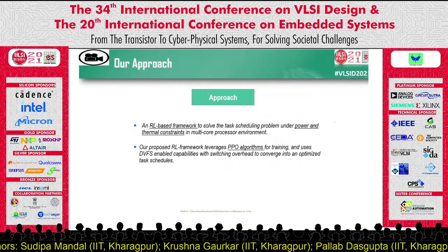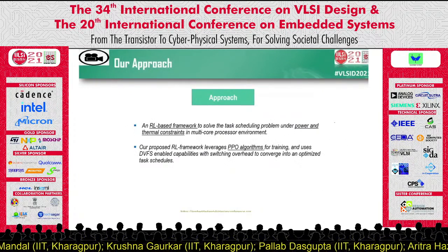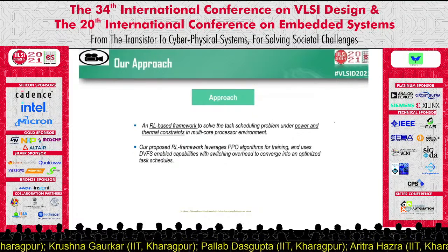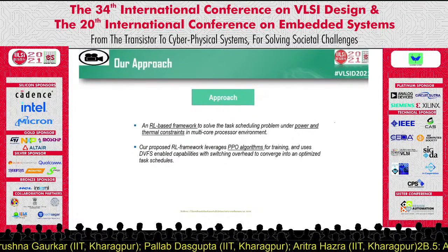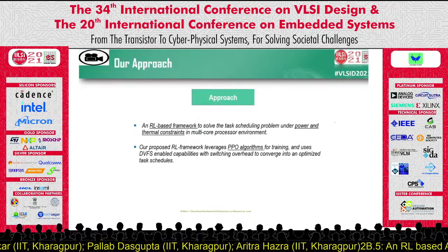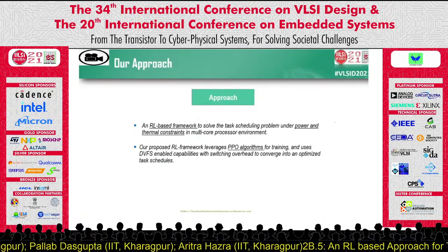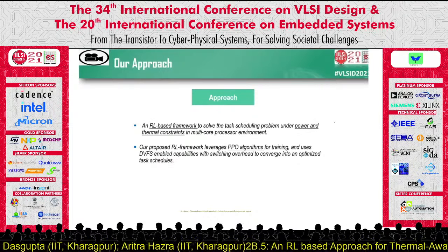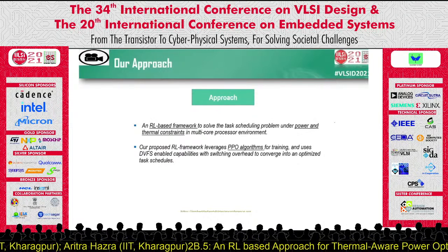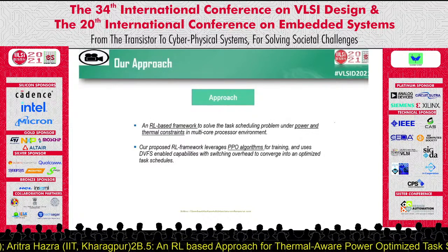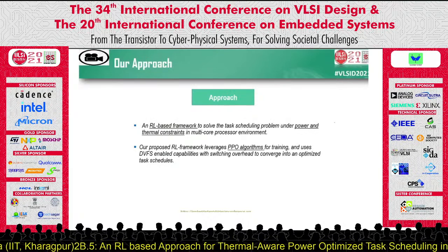To overcome those challenges, we introduce an RL-based framework to solve the task scheduling problem under power and thermal constraints in multi-core processor environment. The framework leverages PPO algorithms for training and uses DVFS-enabled capabilities with switching overhead to converge into an optimized task schedule.